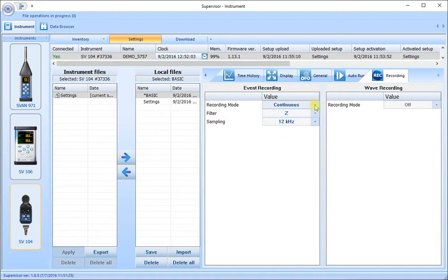Rather than a continuous recording, which we really wouldn't want unless we have a particular reason to have an 8-hour full audio recording, we would normally want to use some form of trigger. So we have two methods of triggering, either using a slope with the sound level increasing or decreasing, or triggering at a particular level, again either positive or negative going.